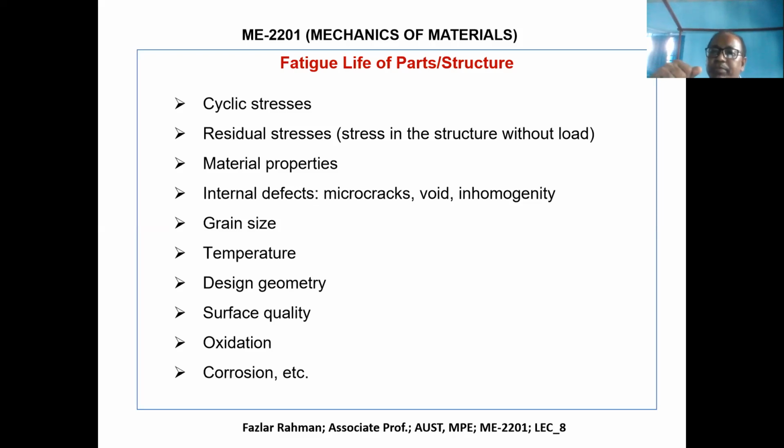When the piston is going upward, it is pushing, so it gets a compressive load, like a column. One time it gets a compressive load, another time a tension load. So one time tension, one time compression. The same thing happens like the wire you bend back and forth. So ultimately, over some years, it fails.